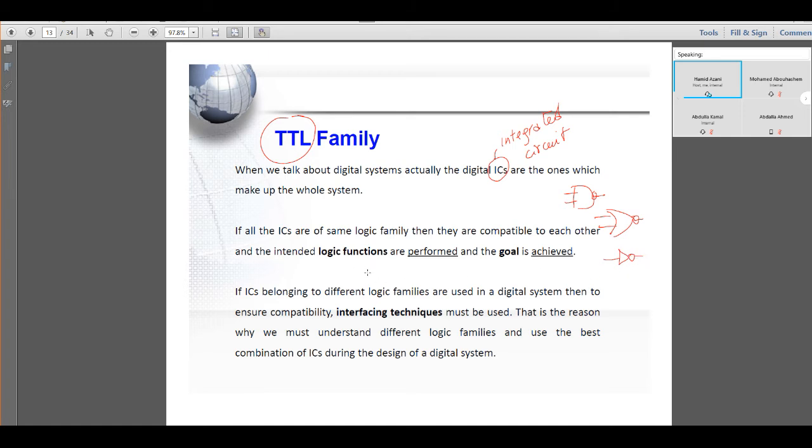Inverter, for example, if in our Boolean expression we have A bar B. So this is the AND gate with an inverted input. We need to do the AND function between two inputs. The second one is a direct, non-inverted input, but the other one has to go through the inverter first. So A should be inverted before we give the two inputs to the AND gate, and we can implement this expression, A bar and B. So the output will be according to those two inputs.